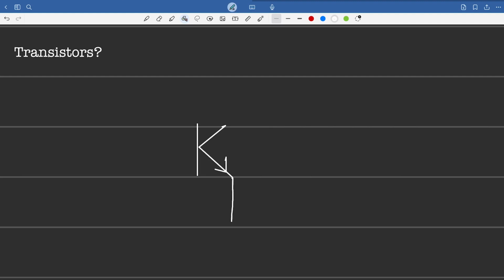This is the emitter. It's going to be generally connected to ground. Over here, we're going to have the base, and the base is going to be connected with a resistor. And usually we have a resistor so that we don't have very high base current, because that kind of messes things up, and we keep the base current very small to avoid destruction of the whole NPN because it overheats.